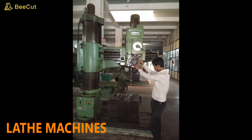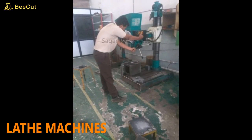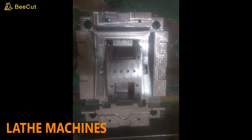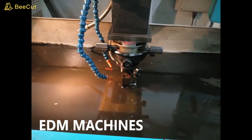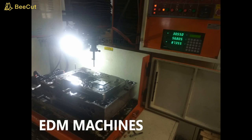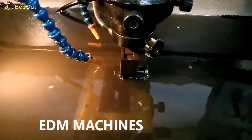Drilling machines are used to make holes in the clamping platens for screws, tapping, Allen bolts for clamping, etc. This can be done in a vertical drilling machine. Surface grinding machines are used for the surface finish of the mold platen after the complete mold trial is taken. The EDM machine, known as the electric discharge machine, is used to cut complex shapes and sizes of metal by means of electric discharge.